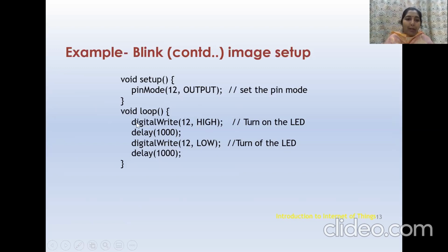If you write these two statements continuously, digitalWrite(12, HIGH) and digitalWrite(12, LOW), the LED will go to the on state and off state continuously, which cannot be recognized by our eyes. It will just display as flashing, or we may even observe it as continuously in the on state. So to observe the difference between the on state and off state, we use the delay statement.